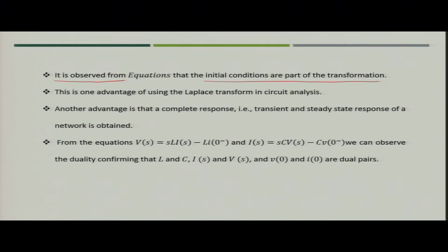Now, from these equations we observe that the initial conditions are now part of the transformation. So, we need not worry about how to incorporate the initial conditions in the S domain, because the S domain equations take care of initial conditions also. This is one of the biggest advantages of using Laplace transform in circuit analysis. Another advantage is that it gives you a complete response, which includes the transient as well as the steady state response of the circuit.